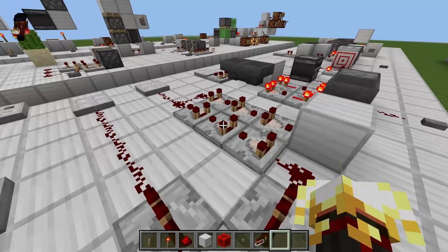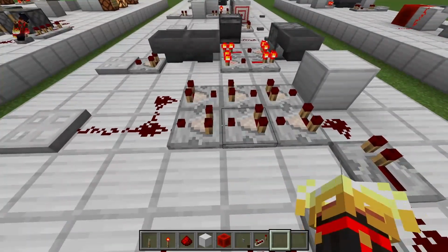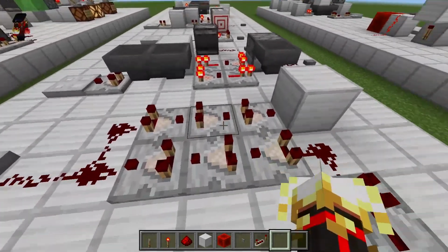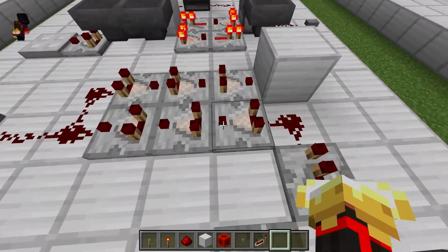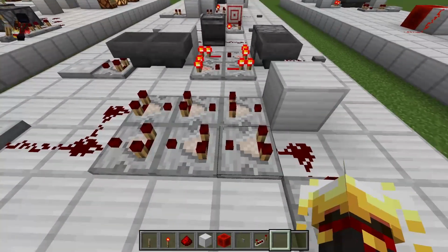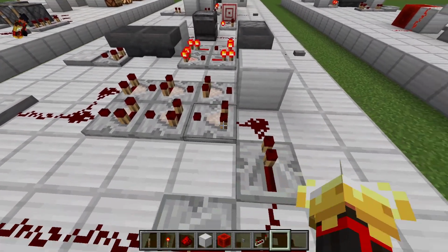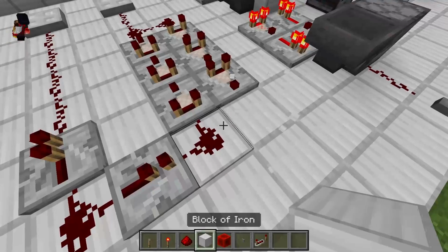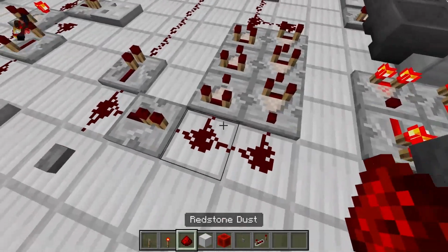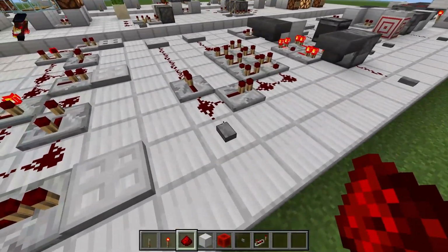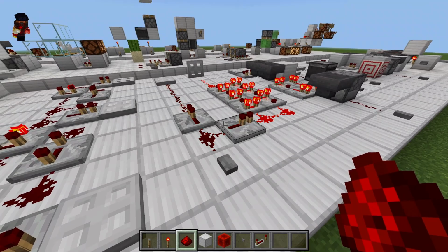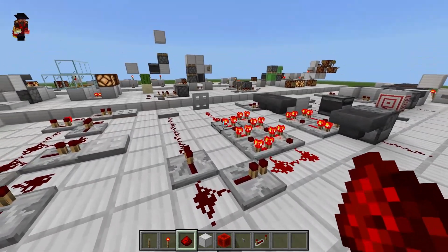However, you have to be careful that the pulse going in has to be able to encompass all comparators. So for these 6 comparators here, we need at least a 6 tick pulse to go in. If we remove the block here, you can see it can decay 1 here and decay once there. So it will decrease a lot faster.